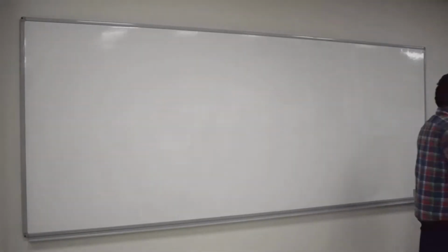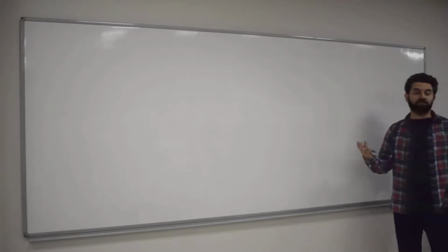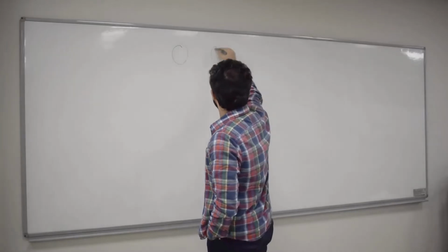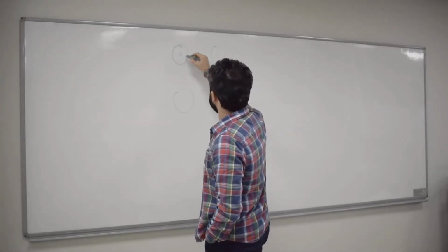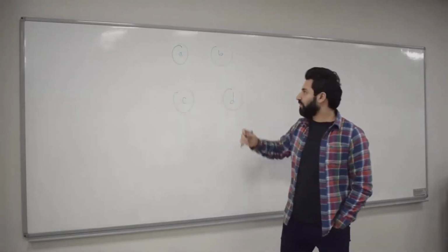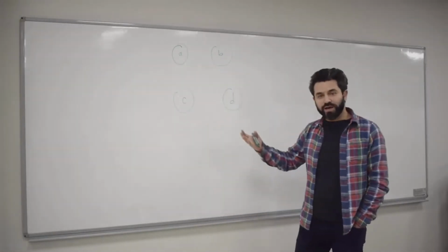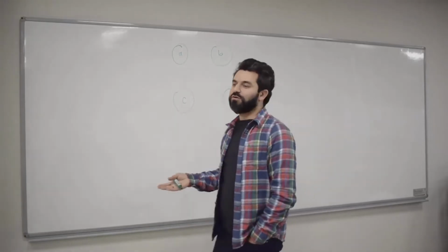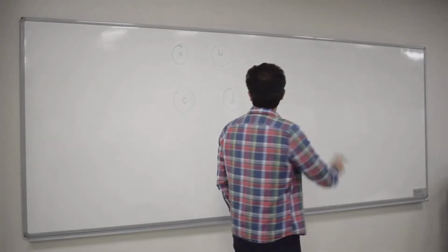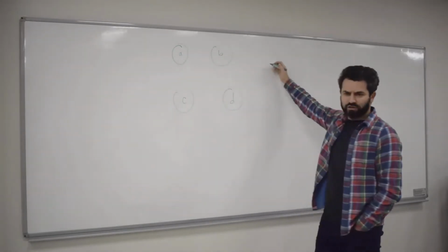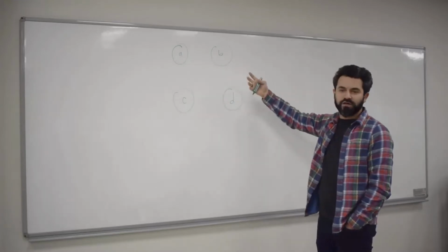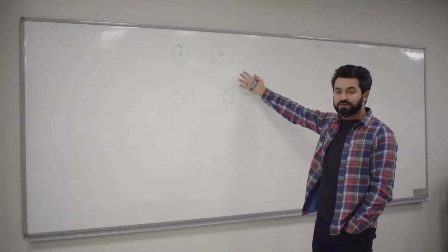That was one of the things. The other problem was the state assignment problem, right? Once you come up with states, for instance, let's say A, B, C, D, then how are you going to represent A, for example? There is no A in the digital domain. You only have binary numbers, zeros and ones. Therefore, you have to map these A, B, C, D to a binary number. This is called coding or encoding. So we're going to be encoding these symbols.